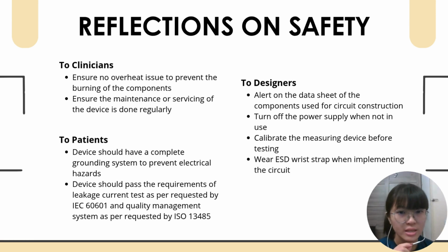For designers, they should pay attention to the datasheet of the components used for the circuit construction and turn off the power supply when not in use. They should also calibrate the measuring device before testing to ensure accurate results and wear ESD restraint when implementing the circuit.